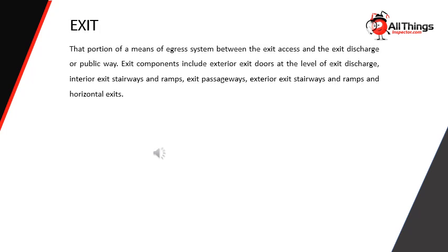Exit, that portion of a means of egress system between the exit access and the exit discharge or public way. Exit components include exterior exit doors at the level of exit discharge, interior exit stairways and ramps, exit passageways, exterior exit stairways and ramps, and horizontal exits.